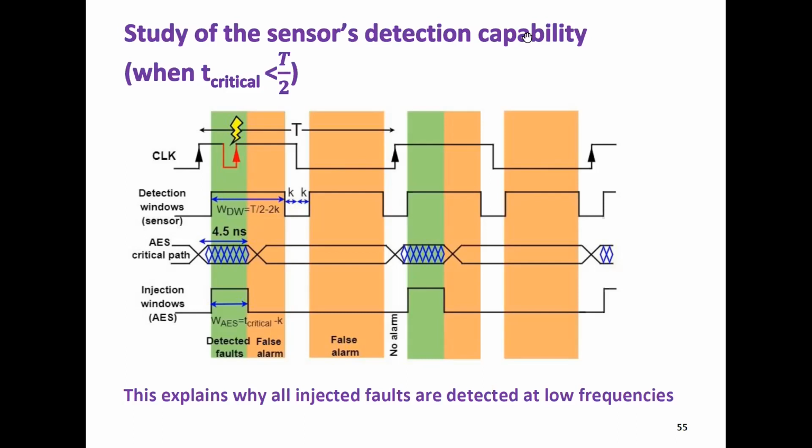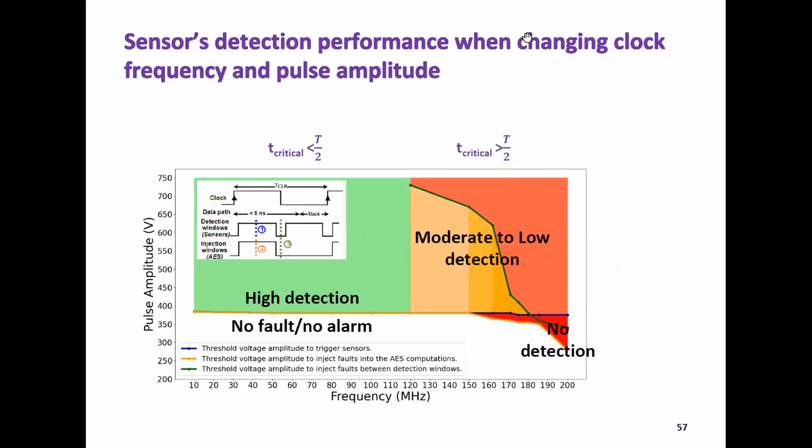Actually, for the designer, the critical path is 4.5 nanoseconds. It never runs at, let's say, 20 megahertz, because you have a big slack and you're wasting time. That is why I mentioned here that a design proposed, for example, for 200 megahertz maximum clock frequency, is really around 170 megahertz, just to respect the process, voltage, and temperature margins. So it is good at low frequency, but not good for the designer in real life, as it happens in industry.